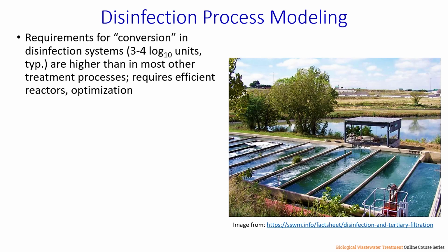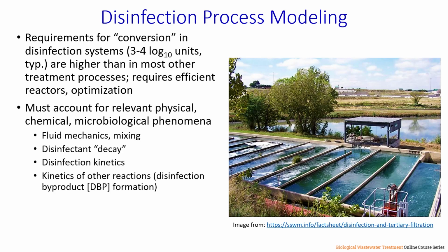In turn, this also represents a great opportunity for the incorporation of numerical models to simulate the behavior of these systems. These numerical models are fairly complex because they need to account for the relevant physical, chemical, and microbiological phenomena that govern the performance of disinfection systems. That includes specifically fluid mechanics and mixing, the reactions that lead to decay of disinfectants, the reactions that are responsible for disinfection, specifically the kinetics of inactivation, as well as the kinetics of other reactions that may take place in the system, such as formation of disinfection byproducts.